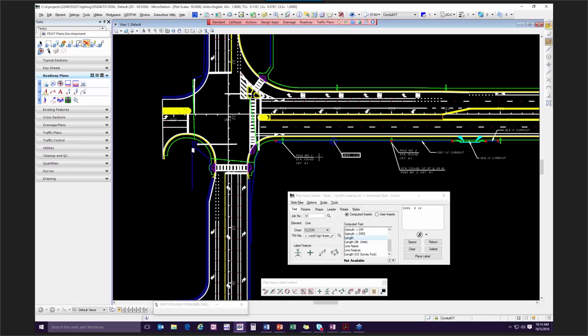It's kind of different, because otherwise trying to get into these labels the way that Geopack creates them, like cells, it's difficult to do what you need to do sometimes with these labels using regular MicroStation tools. So go through and check out all of the different options that they have down here for helping you out. It's definitely a good thing. But down here is the edit label. Makes it a lot easier to edit those.